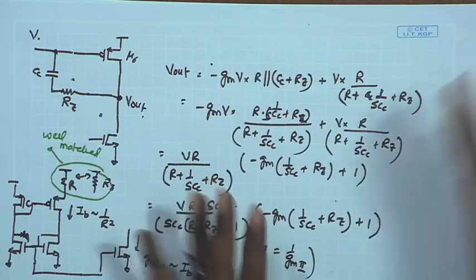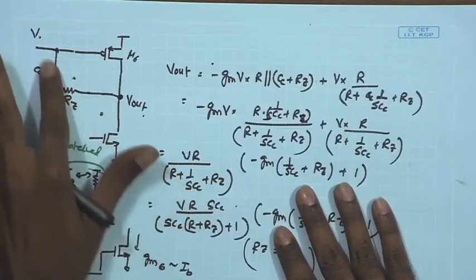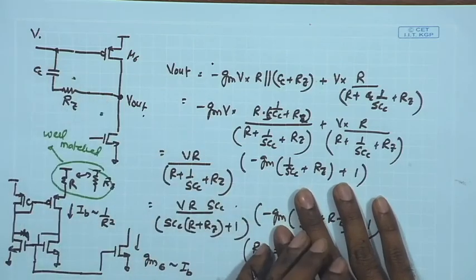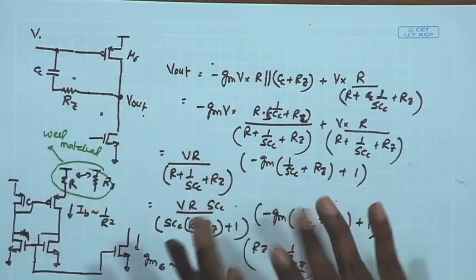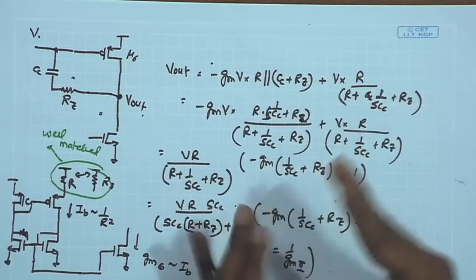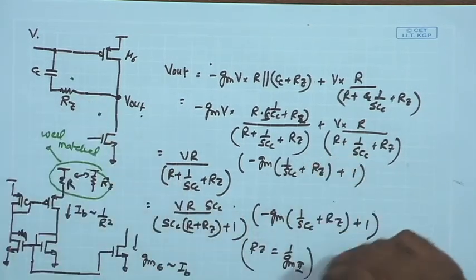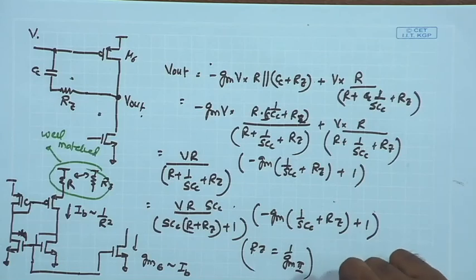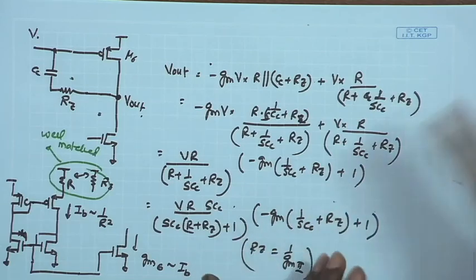Even if you are using other amplifier topologies, like one of the target is to look at folded cascode topologies, where we do not have this problem of 0. We do not need to have Miller compensation. There we have another scheme which is called dominant pole compensation, which is inherently stable, does not give the 0 in the overall response. So we will be looking at an alternate topology also, but the overall concepts remain similar.